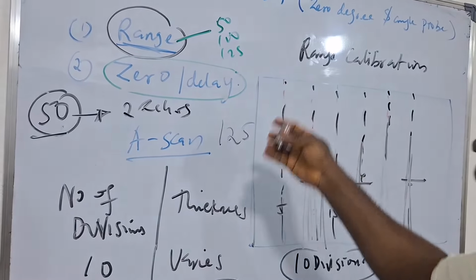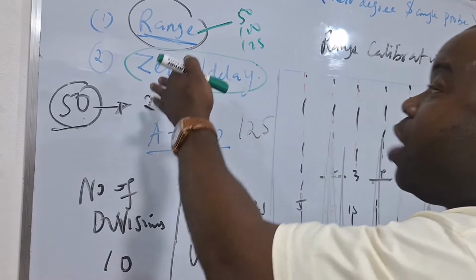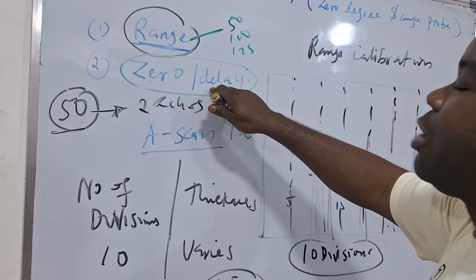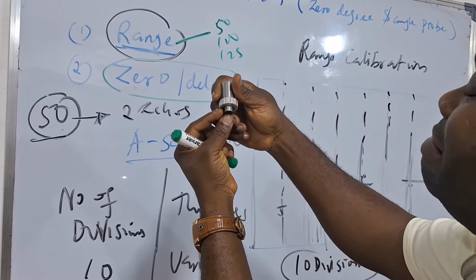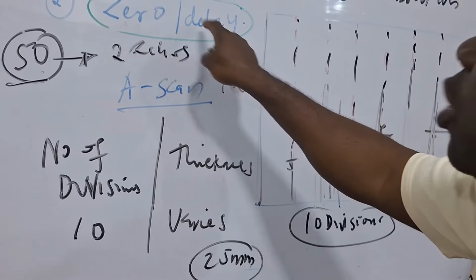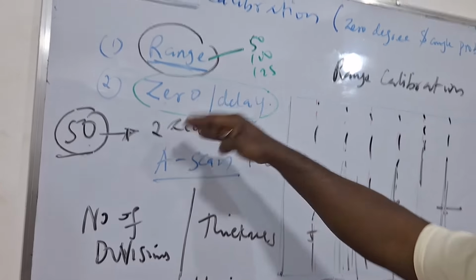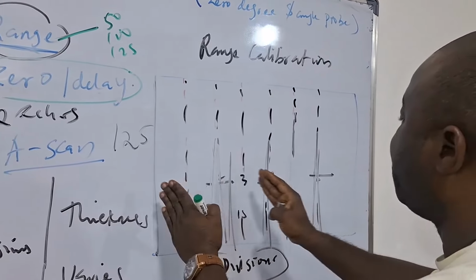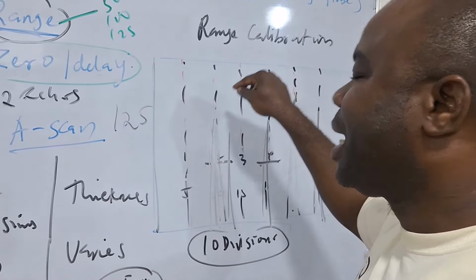In some other cases, you can just adjust 0 and see what happens, if you are not getting the right value, before you start touching your delay. In some other cases where you have a physical wedge on your probe, you need to play around with the delay. So you play around with your 0 and your delay, either one of them or both of them, and you see your echoes jumping around back and forth. That tells you that you have properly calibrated.